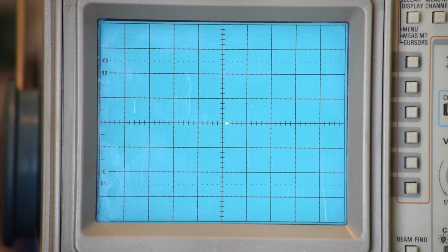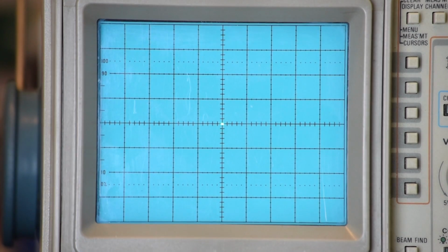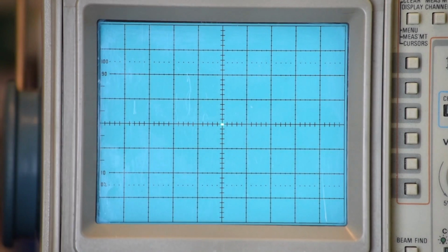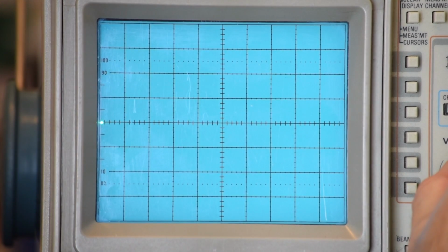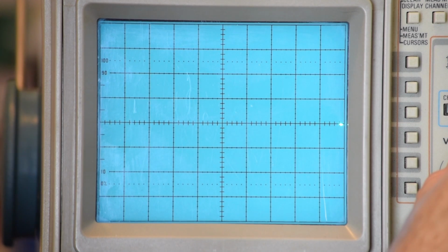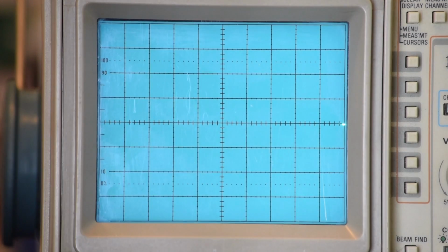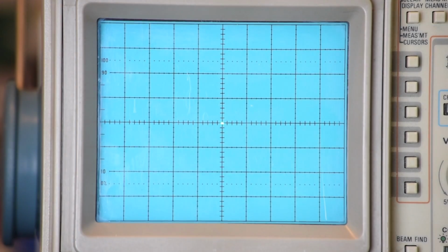And what's a little unusual here is you've got to remember when you're adjusting the x-axis, you actually use the oscilloscope horizontal position, not channel 1 position. So that looks pretty good. So that's the calibration process in pretty close detail.